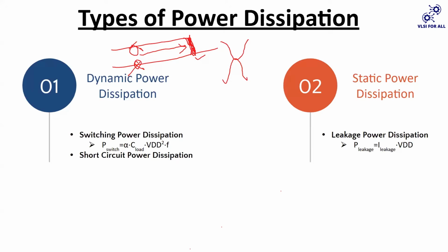Now, in layman's language, if you have to reduce your switching power dissipation, what will you do? Just look at this expression I have given and let me know what I should do. Reduce VDD. Okay. Anyone else? We can play with the activity factor, the frequency, or the load capacitance. Correct, because all four are there.